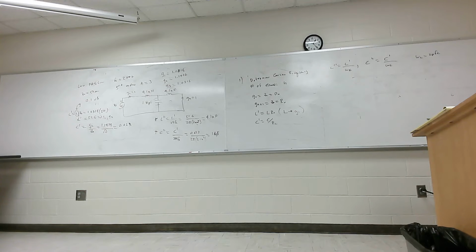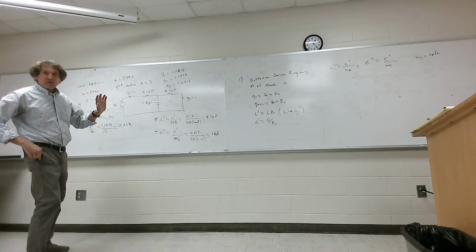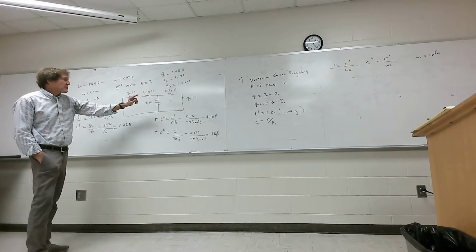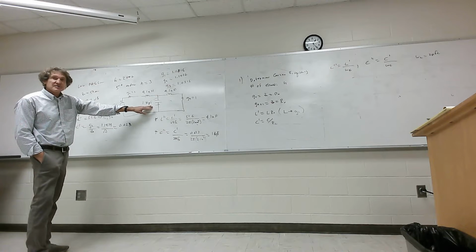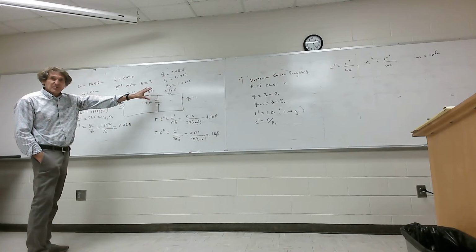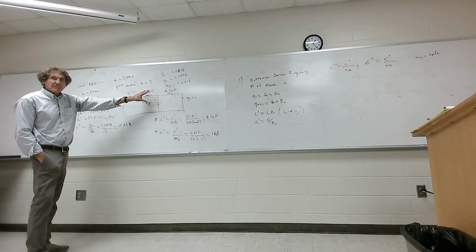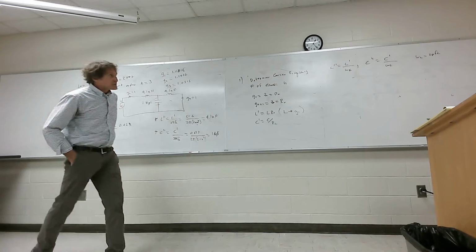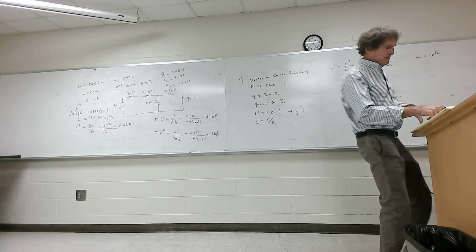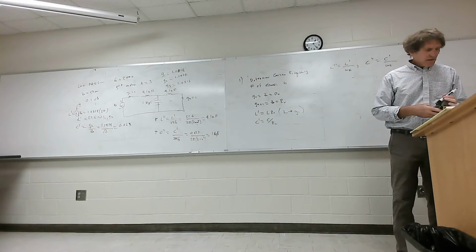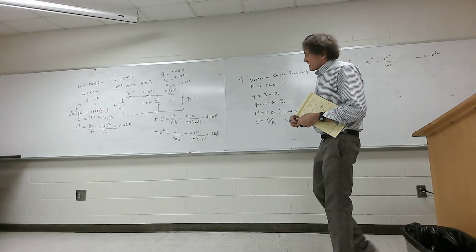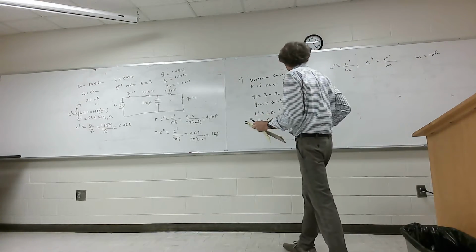The only thing we're going to do is, if we use this configuration and we wanted high pass, where the inductors are, there'll be capacitors. Where the capacitors are, there will be an inductor. This is a T filter. The earlier one was called a pi filter. It had 2 parallel elements, 1 series element. So, getting back to this, that's low pass, but if you wanted to do a high pass filter, I'll put it right here.